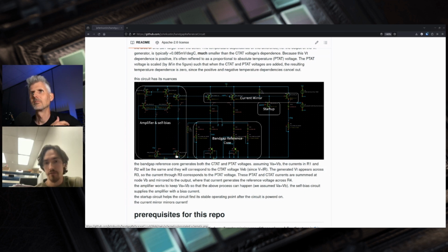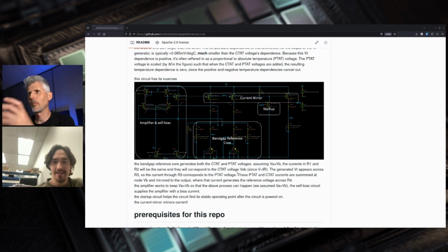And in order to force those two voltages to be the same, you wrap feedback around it. In this case, like you said, this very classical differential pair input, single-ended output amplifier worked well enough for that. And while I have the chance, there's a positive feedback and negative feedback tidbit about this particular circuit, because it's not really hooked up like a classic op-amp.